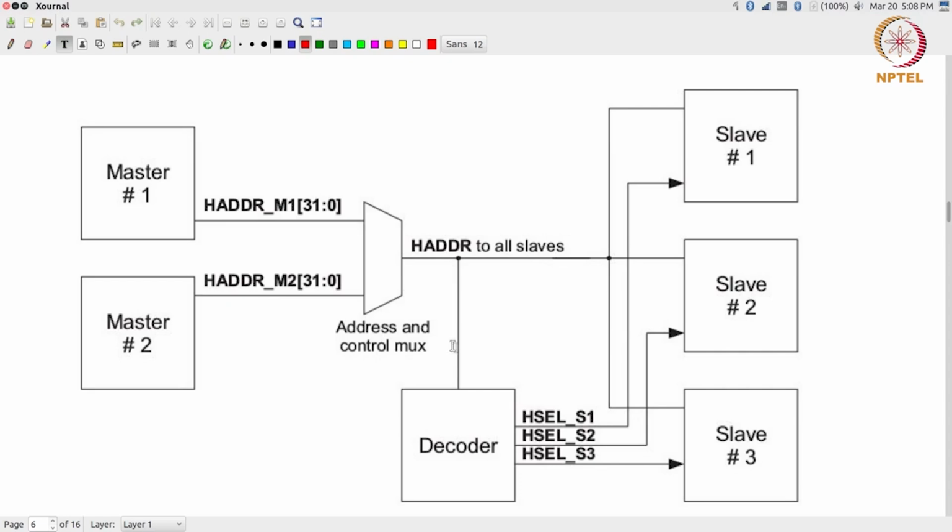They take out part of that 32-bit address, maybe the top 16 bits, and decide that if it matches something like 4120 etc., it corresponds to the GPIO peripheral. If it is some other number, then it corresponds to the FFT peripheral, and therefore it generates a select signal corresponding to that.